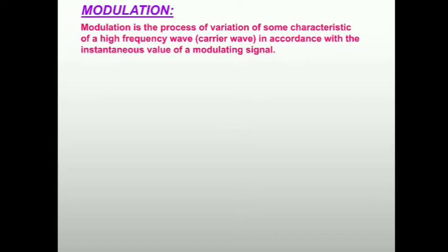Modulation is the process of variation of some characteristics of a high frequency wave in accordance with the instantaneous value of the modulating signal. I already said carrier wave. What is our carrier wave? Is it any new wave? No, it's nothing but a high frequency wave, that is called the carrier wave. Both are the same. The carrier wave signal is usually a sine wave. The carrier wave does not have any information, right? This is the important thing.